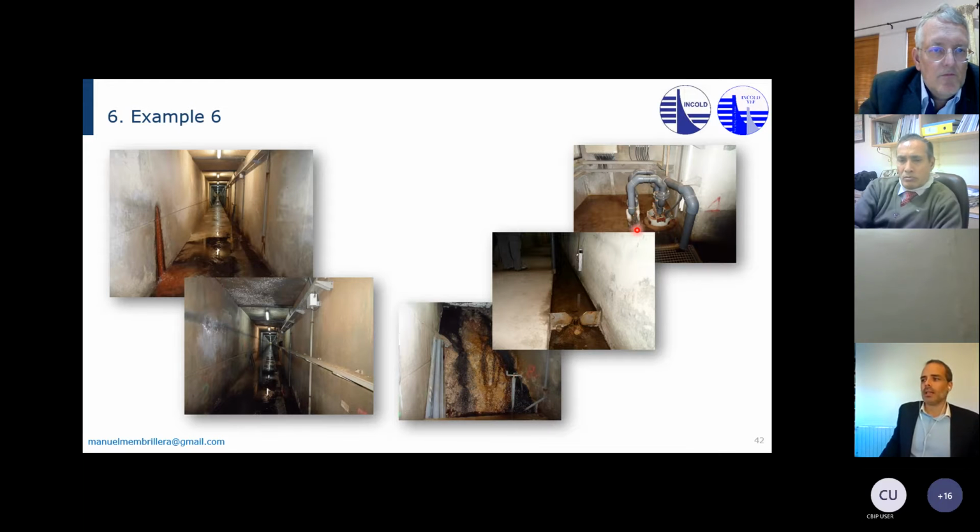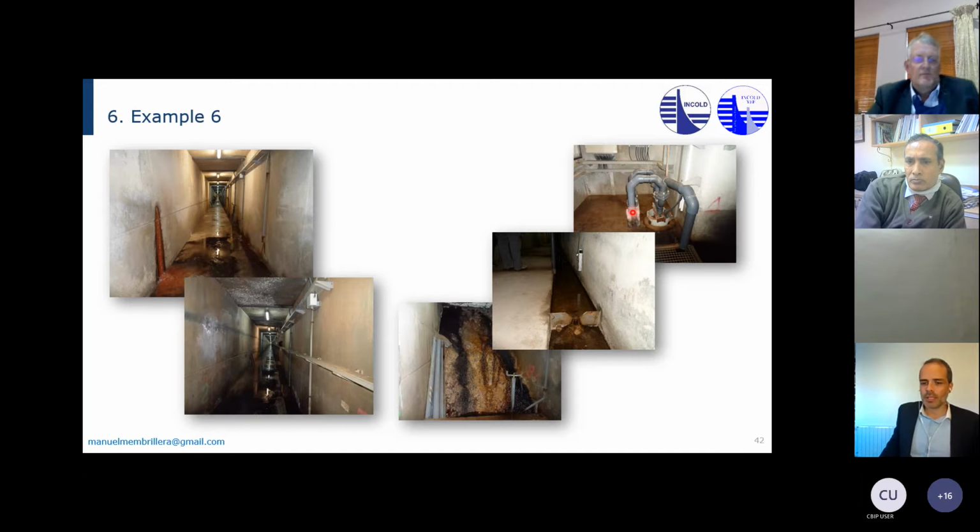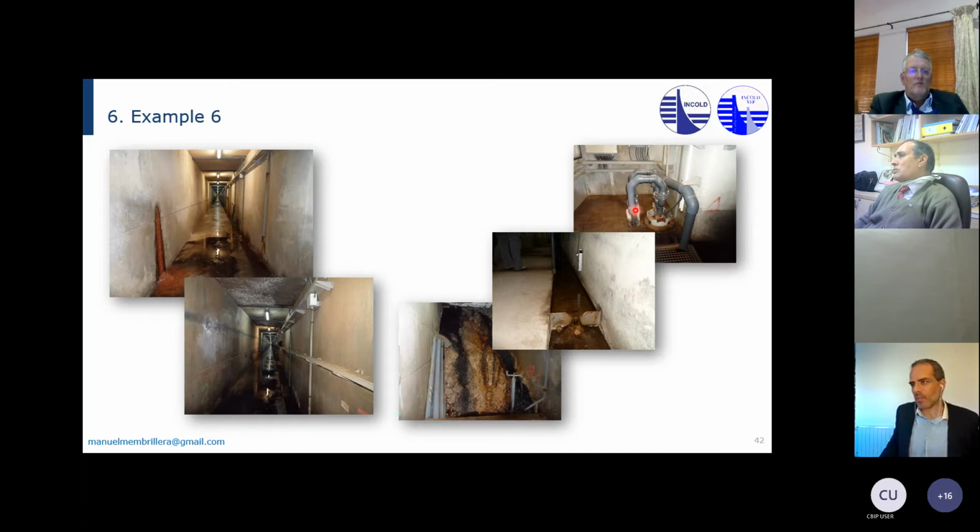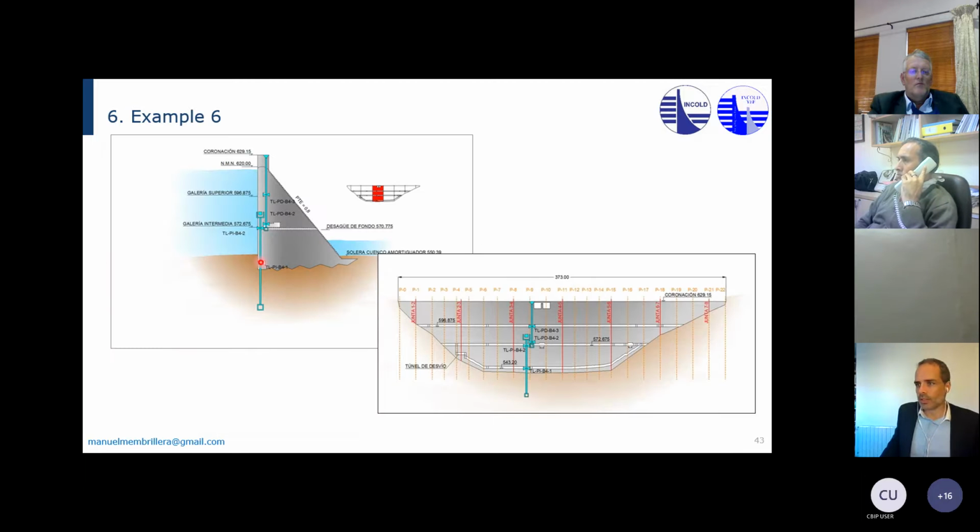This dam and another one in Algeria. These are the pumps in the gallery that is in the perimeter of the dam, deep down. If you have a power supply issue and these pumps stop pumping water, you get this lower gallery, so this is the gallery in the perimeter down here, flooded if those pumps don't have a proper backup.